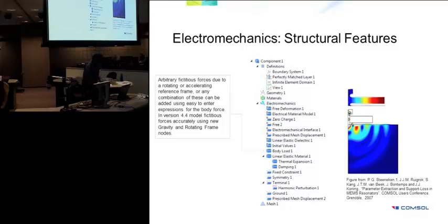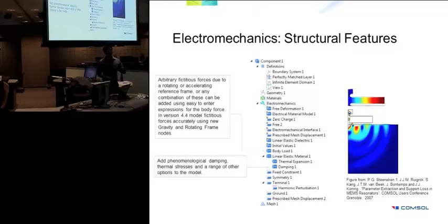There are interfaces for modeling damping. You can model damping explicitly, or you can model damping implicitly. Explicitly meaning you're not telling where the damping is exactly coming from. You just know there is damping and what parameters define the amount of damping. So explicitly, there are two forms of damping: Rayleigh damping, that is viscous damping, or loss factor damping, that is material damping or structural damping due to frictional forces within the material.